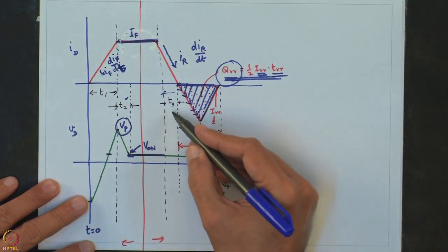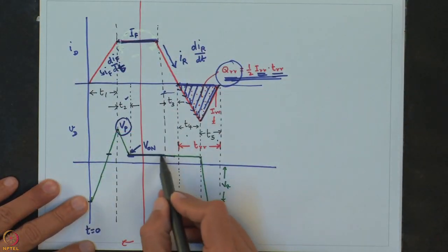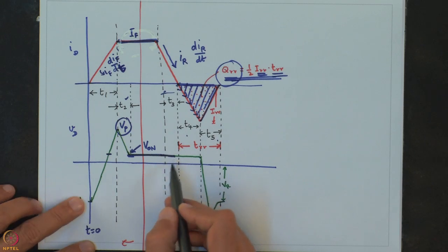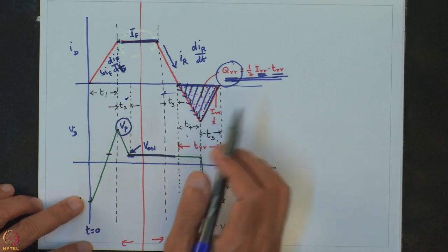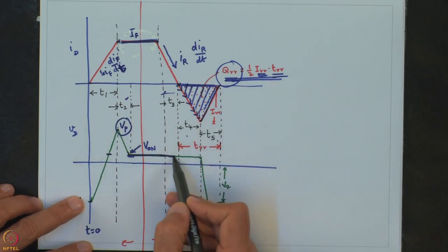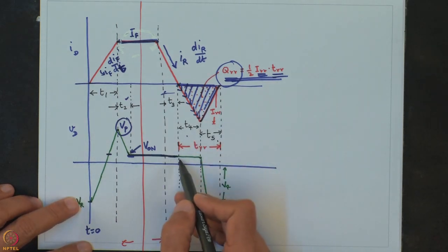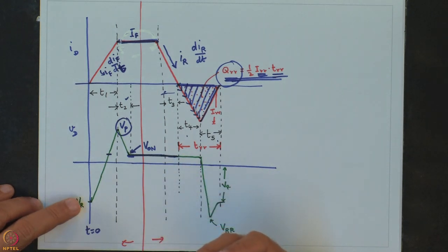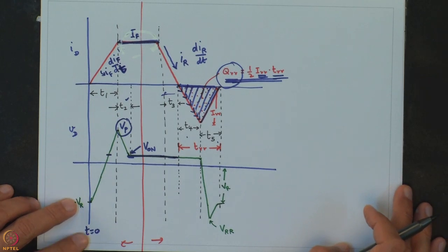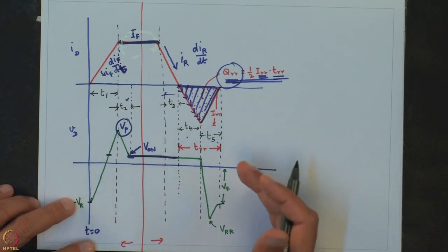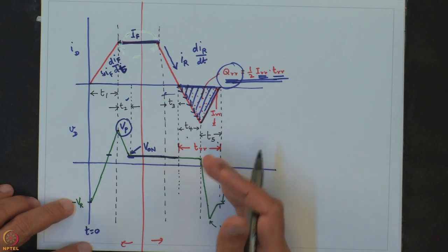before the diode is ready to take the next condition. When the current is just falling during the interval T3, there is hardly any impact on the voltage. So the diode continues to be in its normal on state because the current is still flowing, and it continues like that. The junction of the diode is not yet reverse biased. In fact, the junctions must remain forward biased, so that there is a possibility for the excess carriers to be swept out.